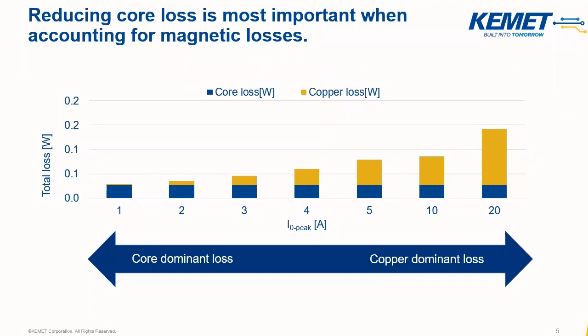Okay. So you get to a certain operating point where it becomes reasonable to reduce your core loss. That's fine, you've got to worry about that. But then there's a point at which, I guess, Peter, you cross over, and those copper losses, those conductor losses, become more important than even the core loss. Absolutely correct. Alex, do you have anything to add to that?